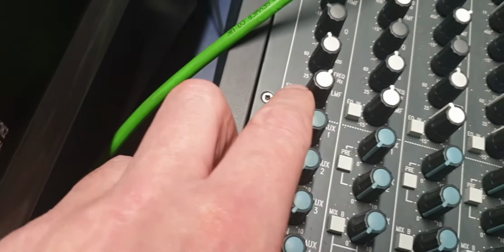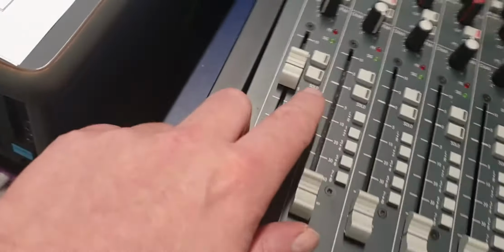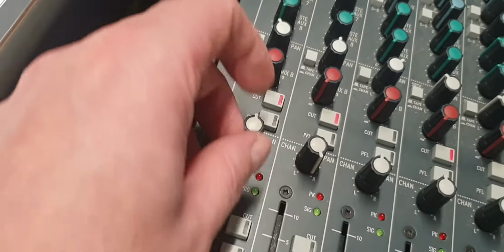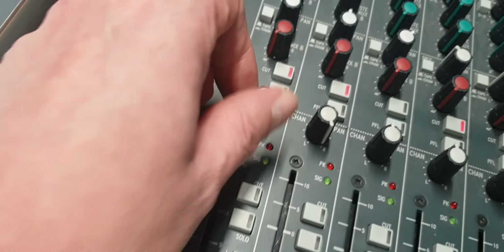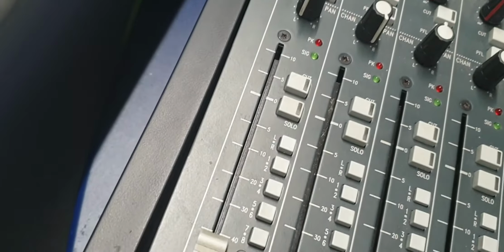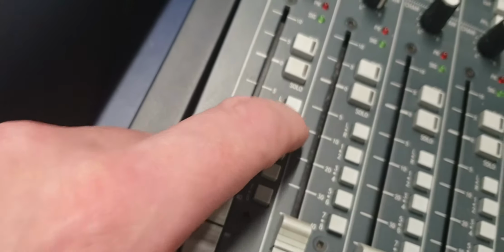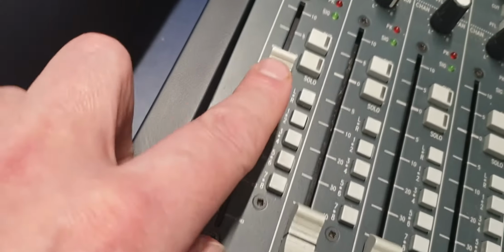Next thing we've done is we've plugged a microphone cable into the back of the desk, and then we need to make sure that all these switches are out, that the EQ is off, that we have the fader panned to the left, because we're going to use a buss assign button, and these are located here where my big finger is. And then we're just going to turn this fader up to 0 dB.